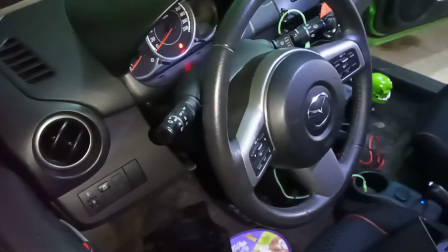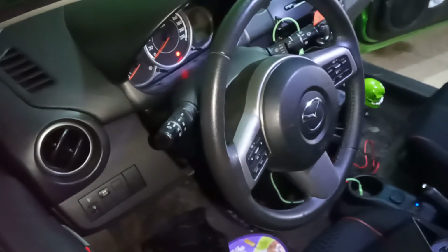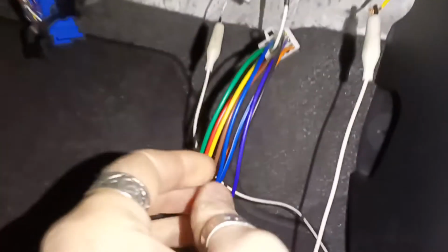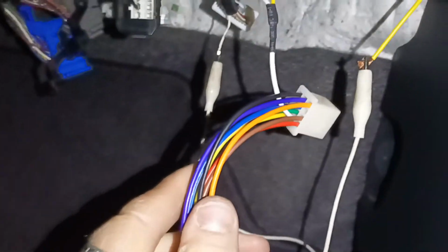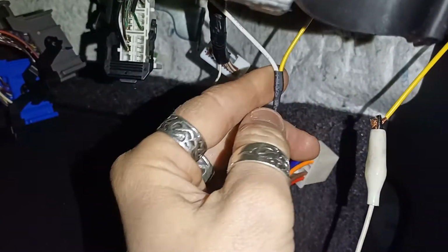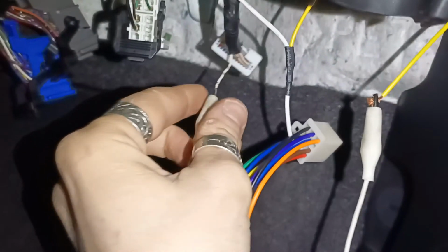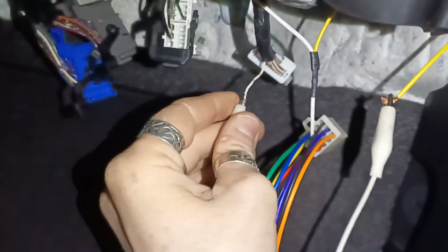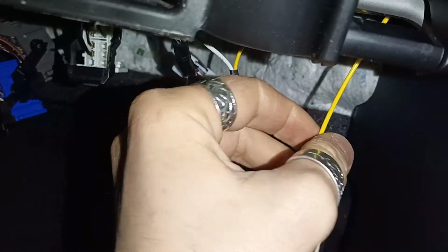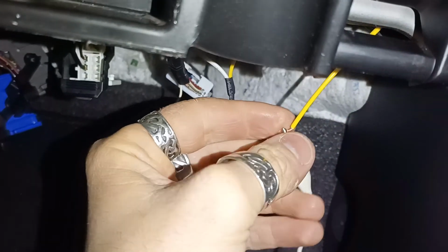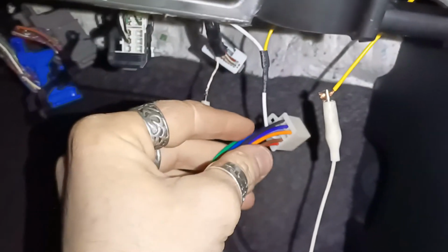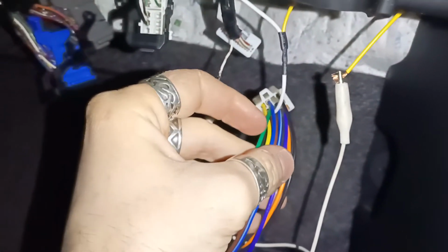Okay, time to actually wire up the automatic part. Okay, I have found all the signals required. So here we have 10 cables. I already showed you how to grab the ignition and how to get the auto pin signal, and this is the control wire for the DRL relay. So these are the 3 signals out of the 10 required.